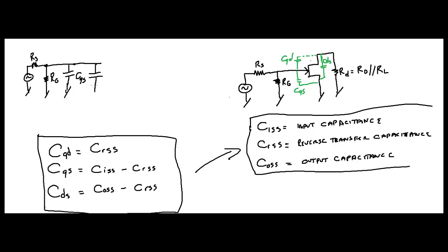So if you need a discussion of that, I recommend you head on over there and take a look at it. But this is a theorem which is used for the calculation of high frequency capacitance in these amplifiers. So then what you're going to have is you're going to have a C in Miller here, right? Let's draw that to ground.